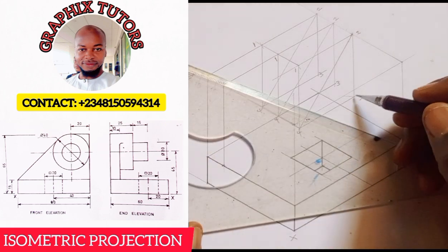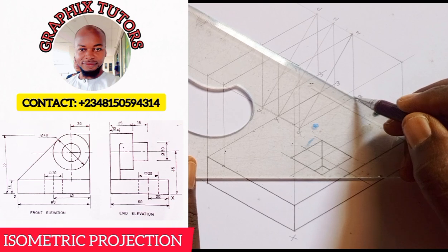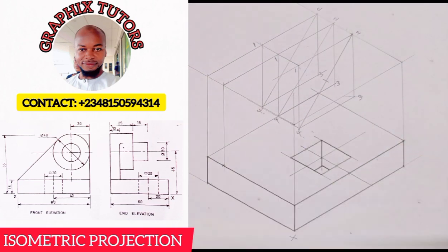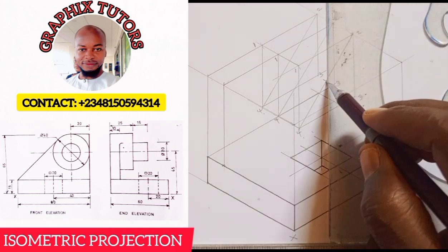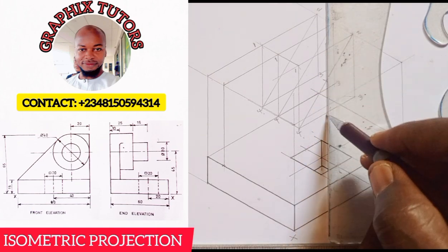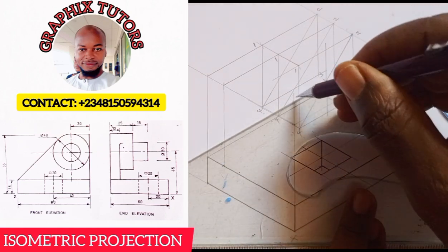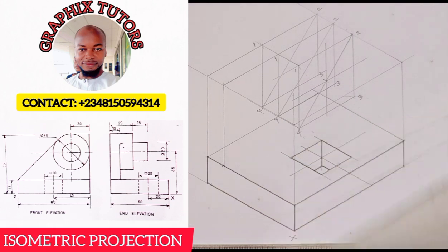Then after that, the next thing is to get the center of that box. I'll just connect as if I want to connect 1 and 2, 1 and then 3. So where it intersects here, that will be the center of that shape. So I'll just draw a vertical line across it this way, and I'll draw another vertical line across it this way.